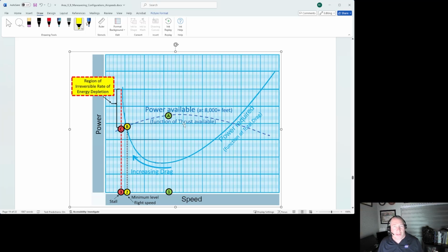Now, one takeaway that I want you to walk away with is that this is a power required chart. If we're sustaining level flight and keeping our power set for this particular point in the chart, for example, where my cursor is, on the solid line below the middle, let's say the minimum level flight speed is 47 knots in this particular general aviation airplane in this clean configuration.